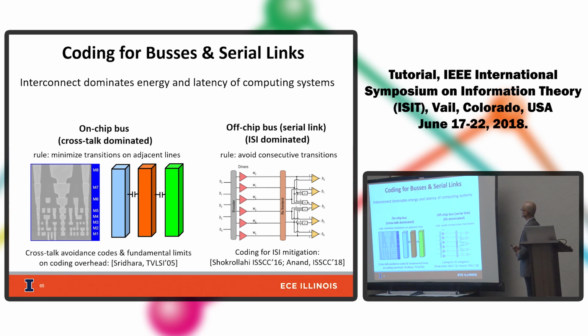Coding for serial buses. In computing systems, in addition to memory, interconnect also dominates energy and latency. There is interconnect on chip and interconnect off chip. On-chip interconnect is dominated by crosstalk. The wires tend to be very tall and thin.